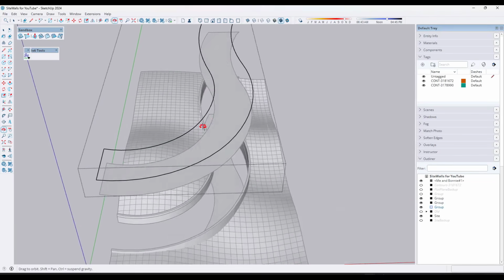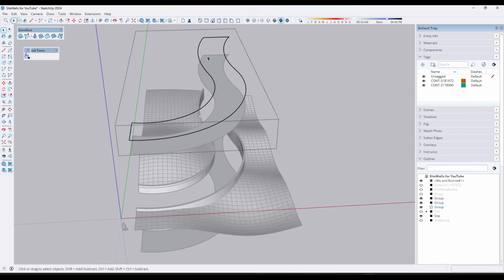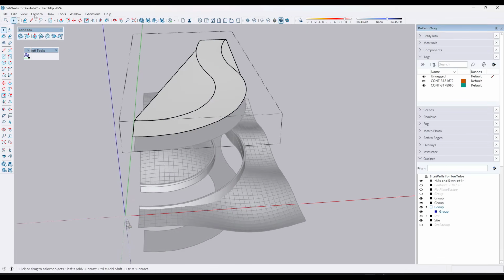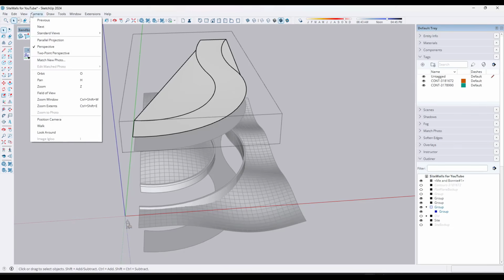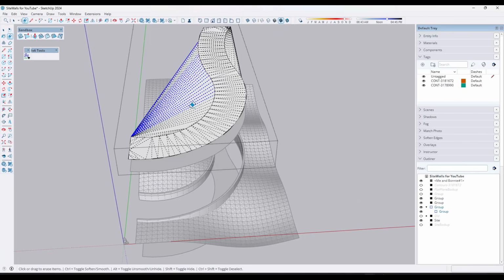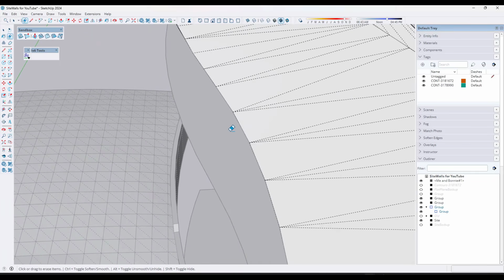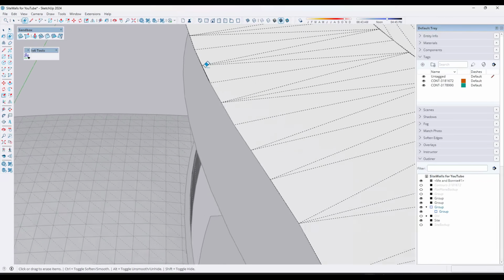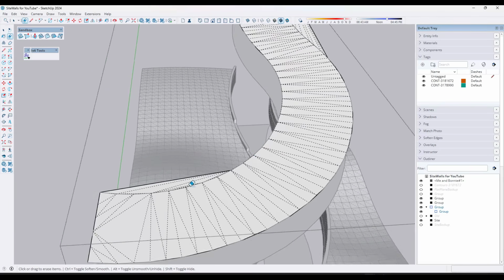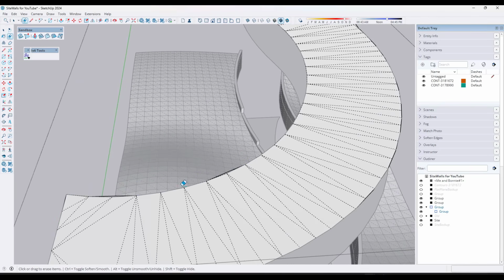There's a few ways that you can create a road, or a surface, in here. One way to do it is just to use the From Contours and Sandbox tools. What that's going to do is create a surface using triangulation. I could do a view hidden geometry in here and you could see this. Then you can just erase out most of these edges. That's a valid way to do this. There's a lot of cleanup involved though, on these edges right here, making sure there are no additional surfaces, but you can definitely do that.